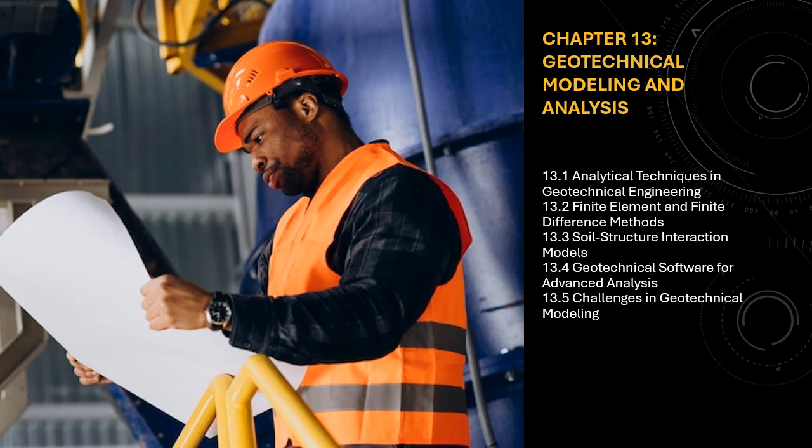The solution involves parameters like soil cohesion, friction angle, foundation geometry, and the depth of the foundation, among others. Modifications of Terzaghi's theory are used for different types of soils and foundation shapes: strip, square, circular, etc.